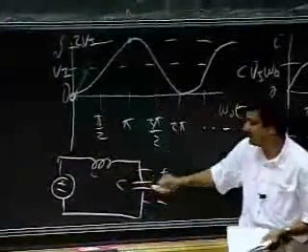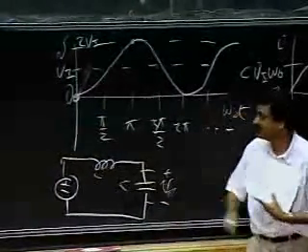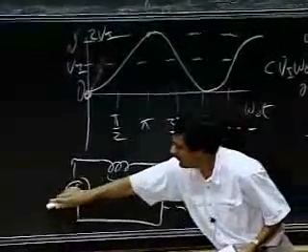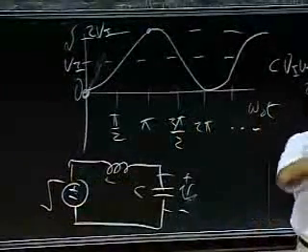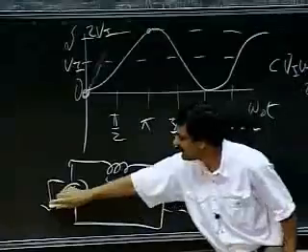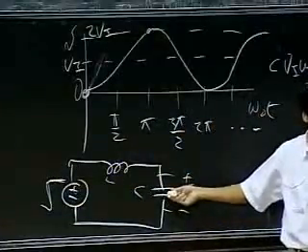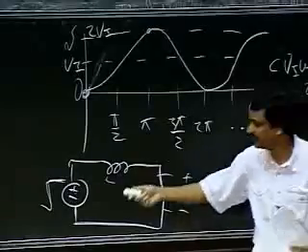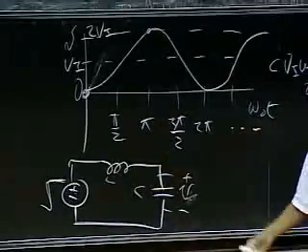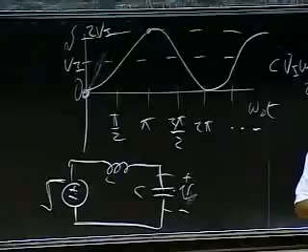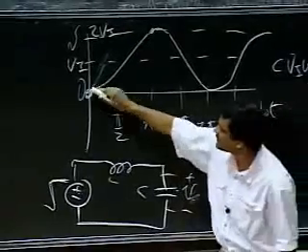I start off with both of them having the states zero, zero current, zero voltage. So apply a step here. Boom, the step comes instantaneously to VI. And notice that the capacitor voltage cannot change instantly, unless there's an infinite pulse of a sort. So this cannot change instantly, and so its voltage starts off being zero.